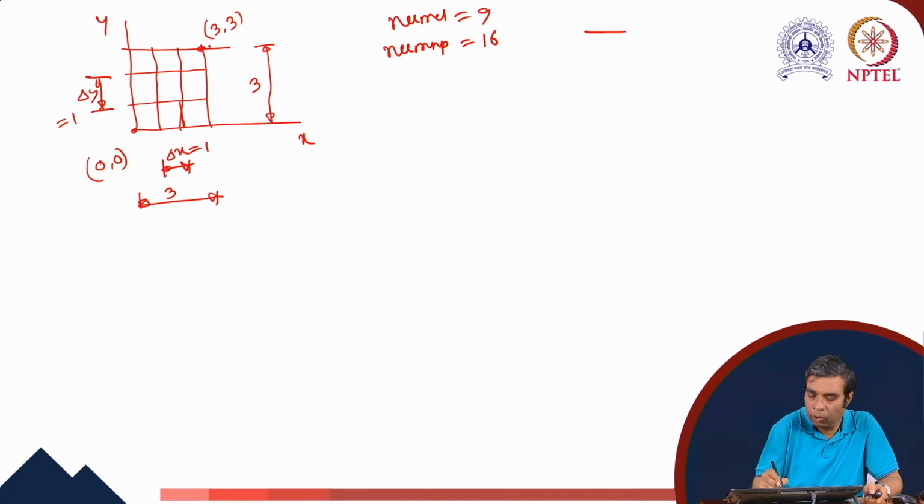Now the local element, we represent it here. This element is known as the bilinear quadrilateral element. It has 4 local nodes, 1, 2, 3 and 4. We perform anti-clockwise or counterclockwise local node numbering.